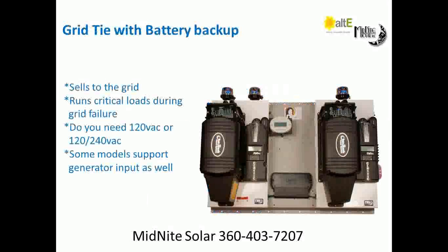I'll touch on it a little bit more now, and a little bit later. The particular inverter you see pictured there does not support generator input very well at all. If it's a grid tie inverter, the generator is usually not stable enough for these inverters to connect to. So if the customer wants grid tie with battery backup and they want to be able to bring in a generator under those extreme conditions, then you probably want to look at an inverter that supports that, and we'll show those as we go through.